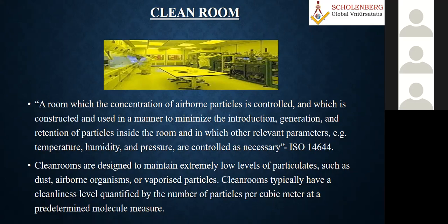Now, if I ask you to define comfort air conditioning, basically it controls only temperature, humidity, maximum air velocity, and cleanliness. But here, it is more than that: particles, airborne particles. That is how the specialty comes as a clean room.